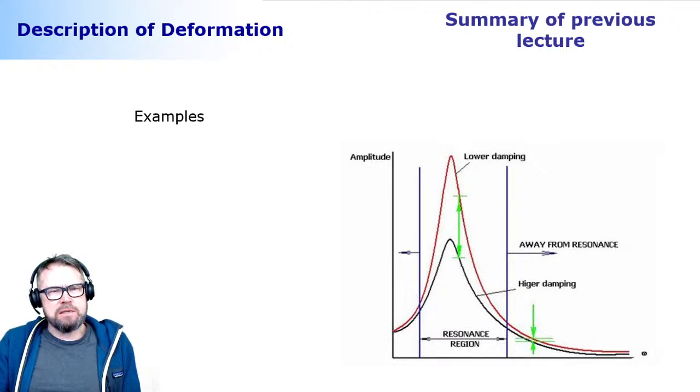I think it can be accounted for in a way, in that the damping affects natural frequencies, but it only starts to affect when the critical damping, which has values from 0 to 1, where 1 is critical damping, is like 0.3 or something like that, which you don't really see in steel or any kind of material that is usually used in engineering structures.